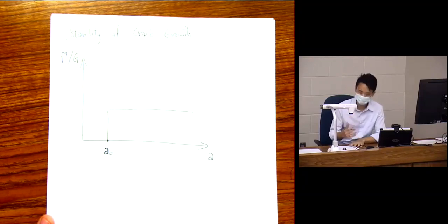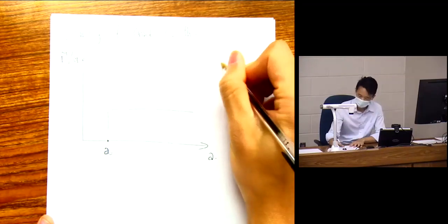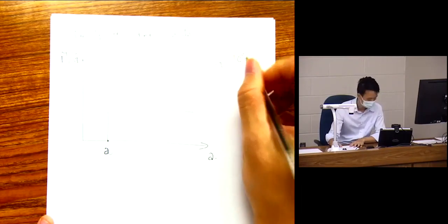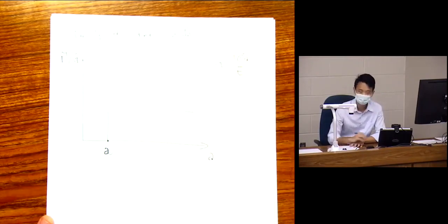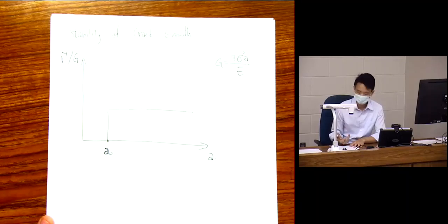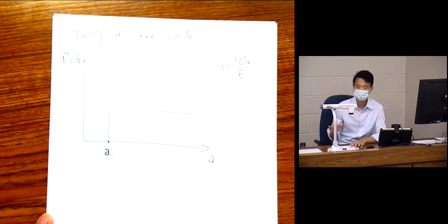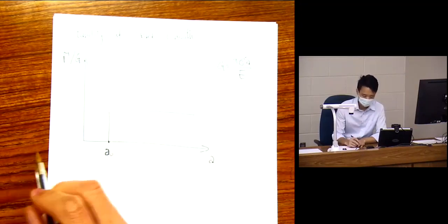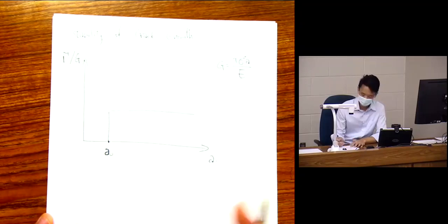And let's look at Griffith, right? So that's the Griffith. This is exactly what Griffith was dealing with, because he had a piece of glass that, now we know, does not have an R curve behavior. It's brittle. Only one fracture energy, does not increase.